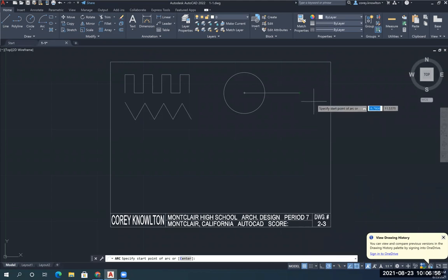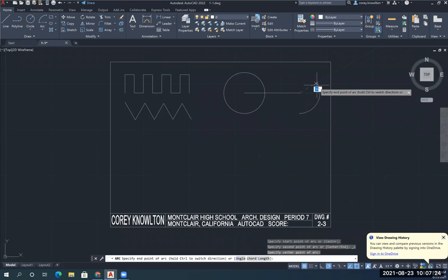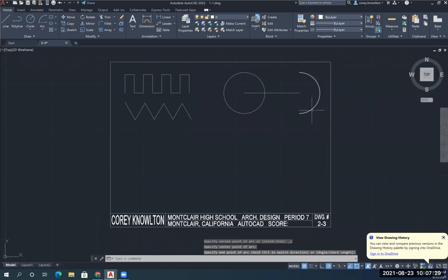So in order to do this start center end, in arc, you start an arc, and an arc draws counterclockwise like this in this direction. So I'm going to put my mouse at the bottom quadrant here, and I'm going to align it with this one here. So here's my start point. Now it's asking for, where's the center? The center is here. And my end point is vertical. Okay, so I started here. Center is here, end is here.